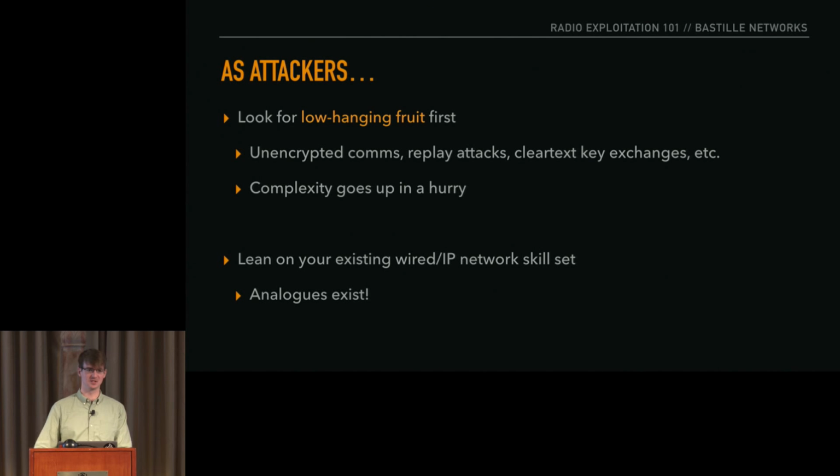As attackers, as you begin to transition into offensively looking at these systems, always go after low-hanging fruit first, because especially with these embedded systems, there are oftentimes very easy ways to knock them over, such as things just being unencrypted, unauthenticated, no sequence numbers, so you can do replay attacks, things like that. Oftentimes they use primitive cryptography, where you can grab a key out of the air and then plug that back into your transmitter and keep running with that.